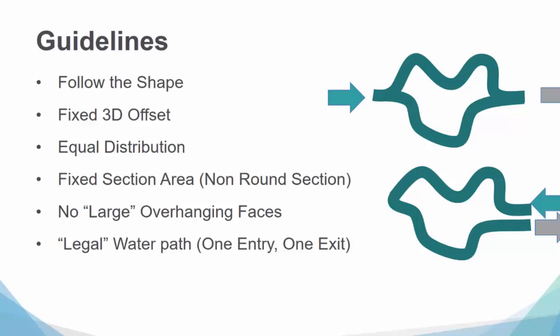A lot of people, when they first start, wonder what size of water line do I choose? How big? What shape? There's a lot of questions and uncertainty. A lot of the time you can just start with what you know. If you've been doing molds and been drilling a 7/16 diameter drill line, start with that. You have rules, no doubt, about how far away you want that water line from a mold insert or from the face of a mold, or how far apart you want your water lines to be from one another.